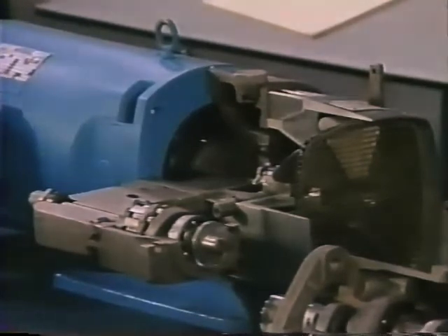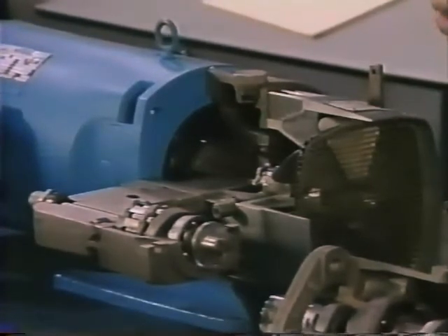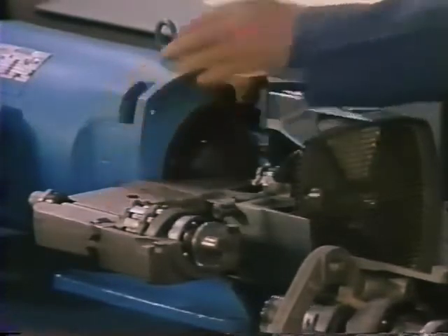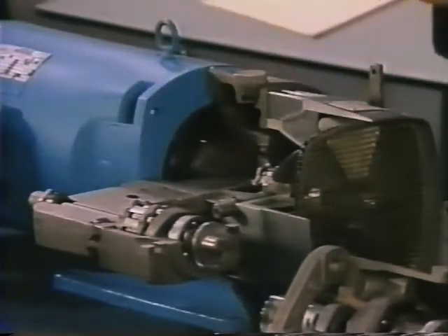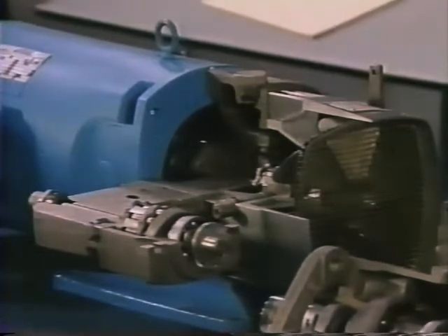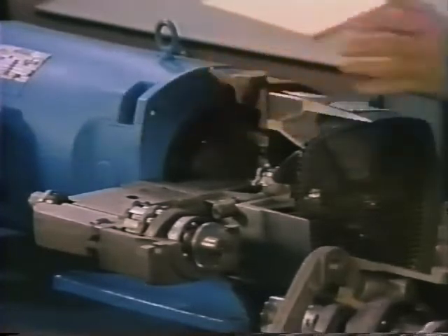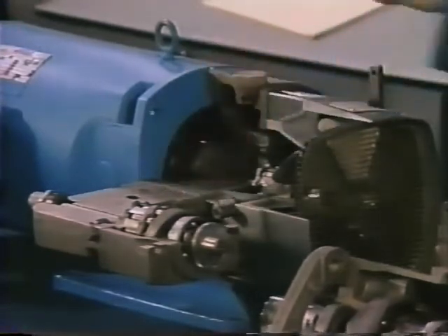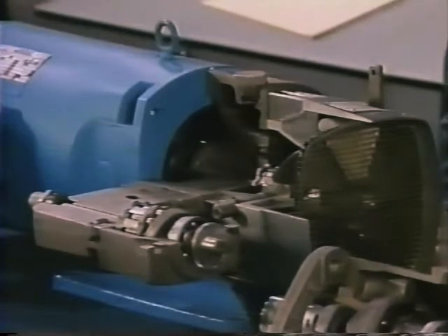Flow paths interconnecting the various components are cast or drilled into this section, combining everything we've discussed into one integral unit. If our application happened to be in a remote or hazardous area, the hydraulic motor could be removed and mounted separately with lines running back to an adapter plate at this point. In this way, the pump, electric motor, and other components could be located out of harm's way.